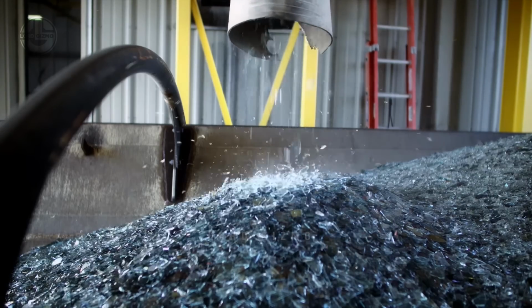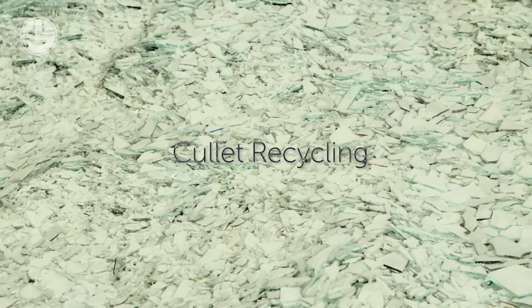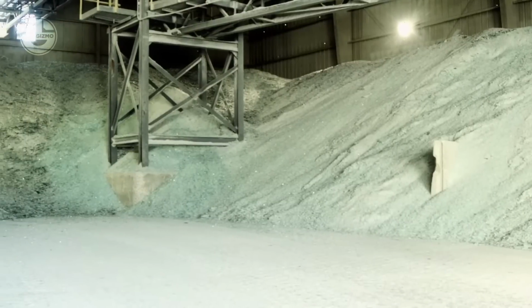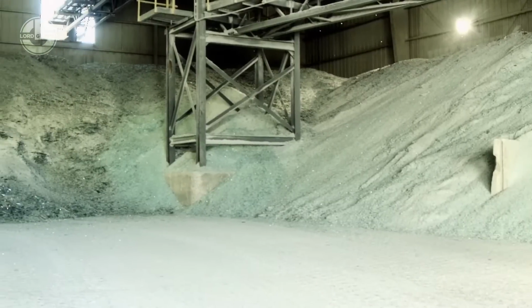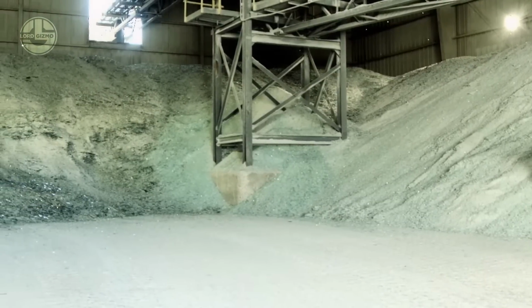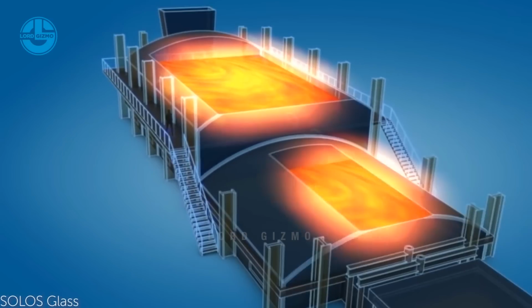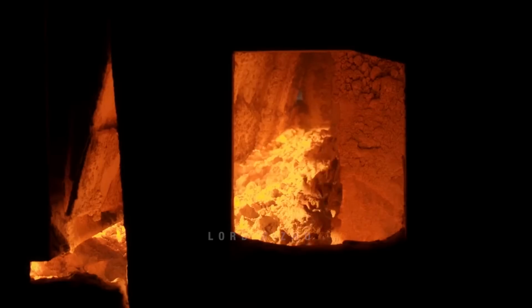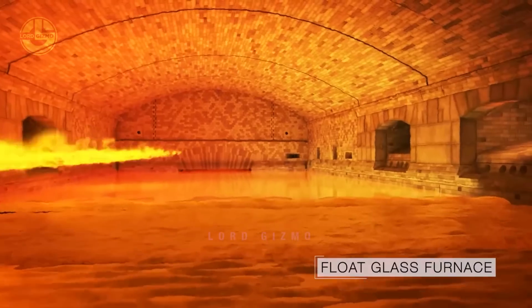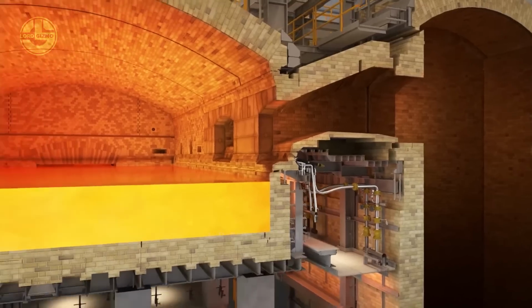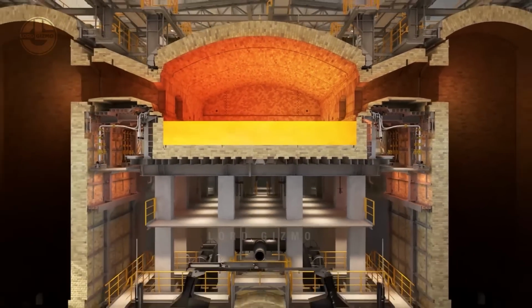The recycling of wasted glass is known as cullet recycling. It is also mixed with batched material, which saves up to 15% of the new raw material. Next, the fully batched material is fed to a large furnace. It melts down the glass material at a temperature of up to 3,000 Fahrenheit, and the compound transforms into a several-foot-deep pool of liquid glass after approximately 36 hours.